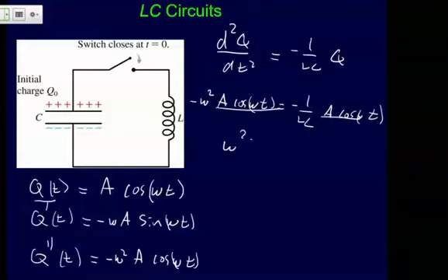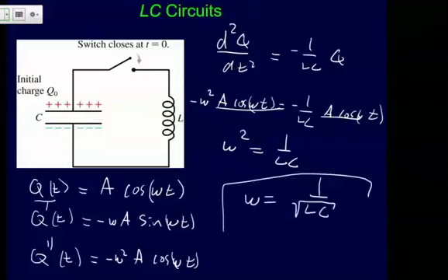And I get this important relationship here. Again, to unpack all this stuff, because this is kind of mathy, we're starting with Kirchhoff's rule. We showed that basically the charge is going to be an oscillatory function. It's going to be a sine function. It's going to oscillate. And better than that, we found that the oscillation frequency is 1 over radical L times C, by going through and doing this here.